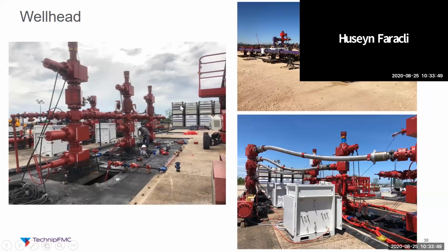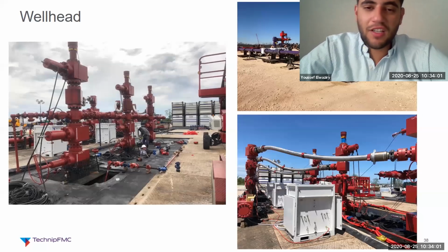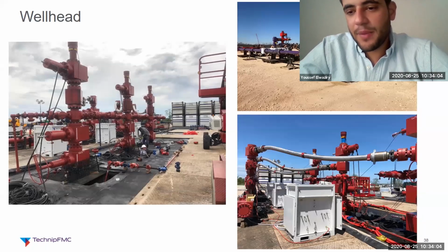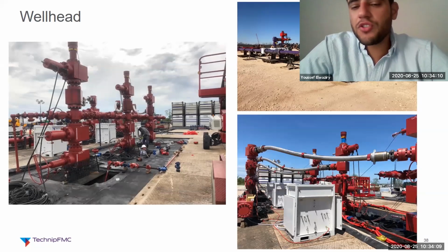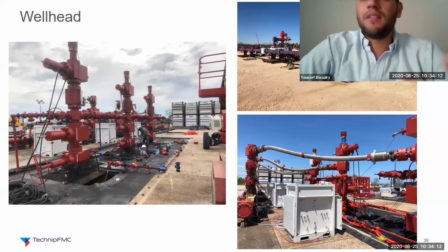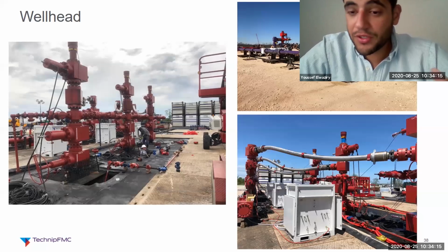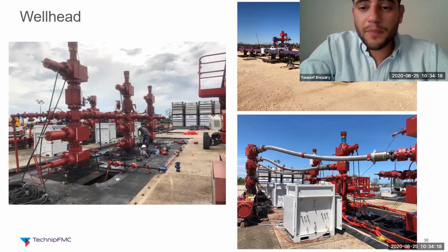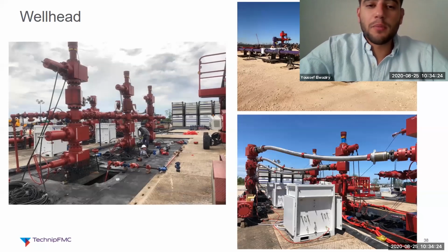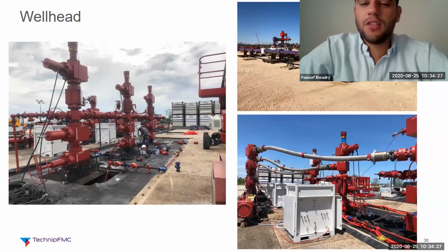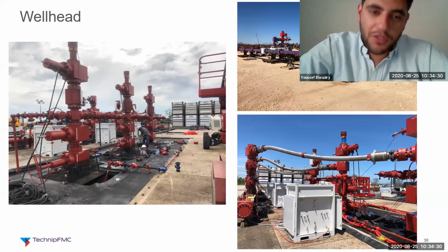The third question, what amount of differential pressure is needed exactly to pump sand up to the top of silos? There's no exact number. It depends on the silo. Some silos can do up to 15, some up to 10. Obviously, the higher the pressure differential is, the quicker you're going to be offloading sand from the truck to the silo. But there is no exact number. Most silos are going to have a pressure differential between 10 and 14.